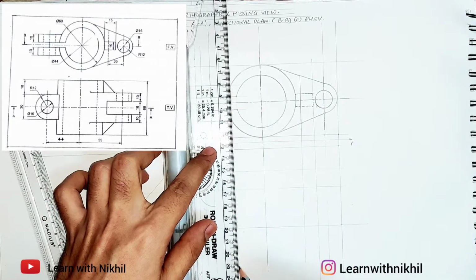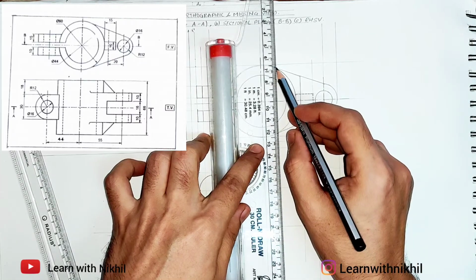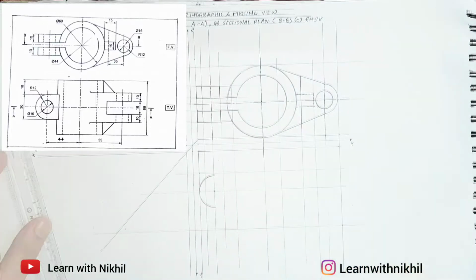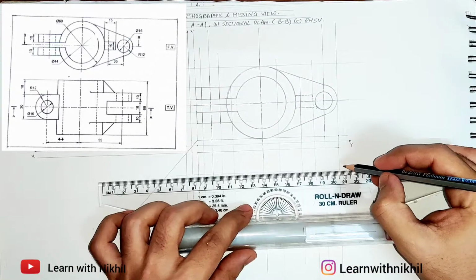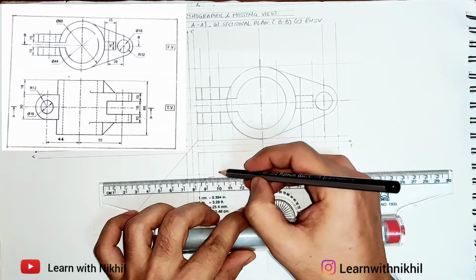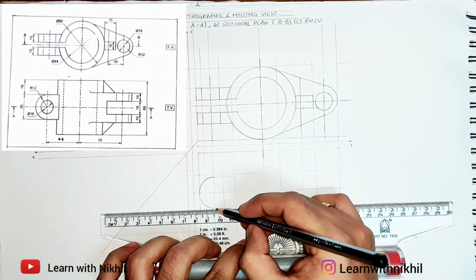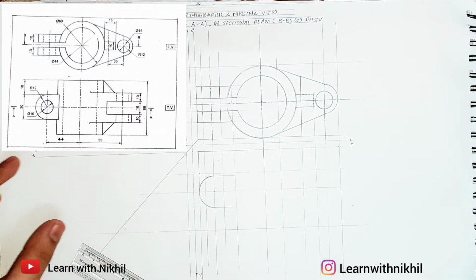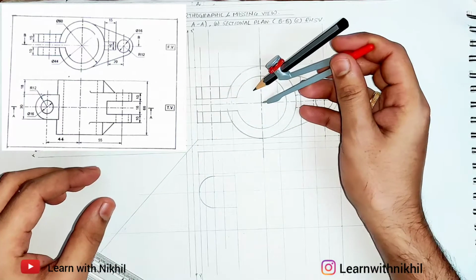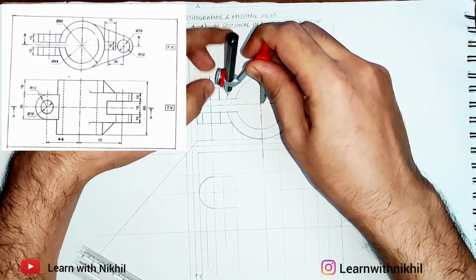I'll take this projection downward where the tangent touches, the line touches the circle, that is the tangent. Take the projection from that also. This line will extend till the circle where it is touched, so I'll extend it. After the section part you have to draw the sectional top view, so according to that we are drawing. I'll just make this part dark.